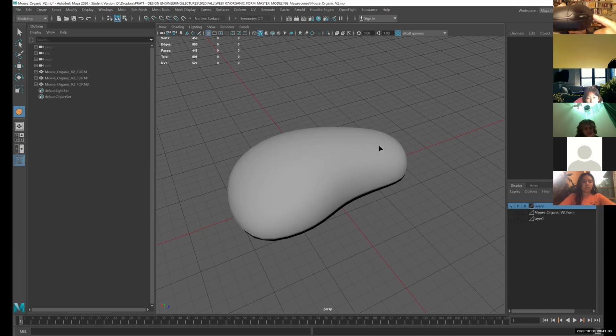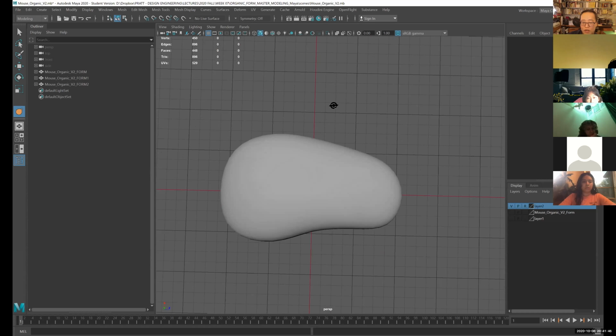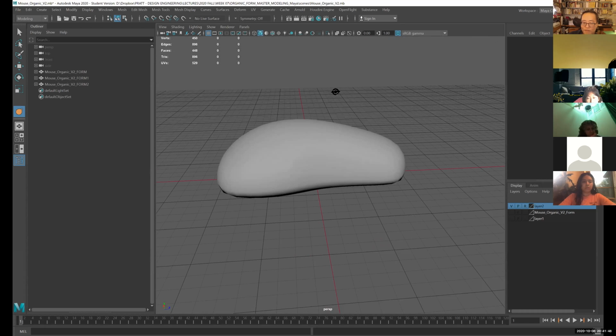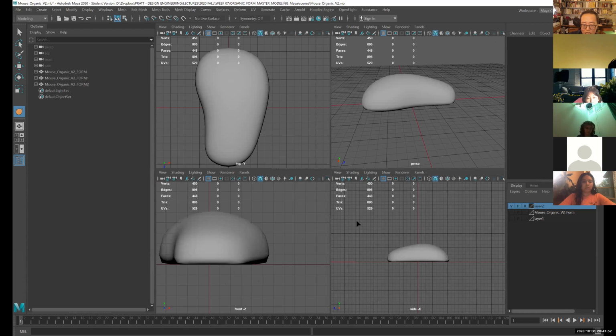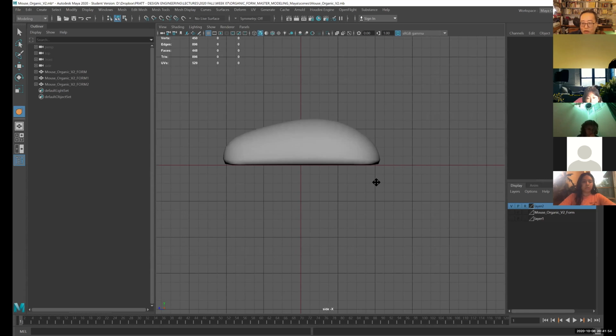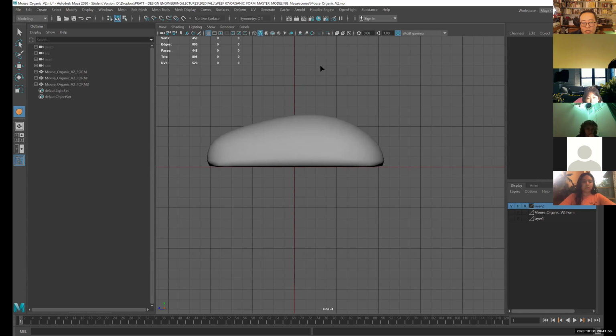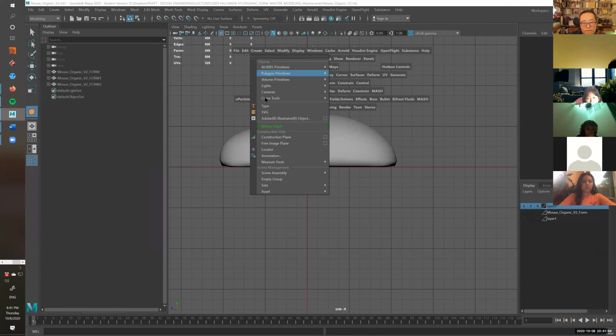So this is one button that is cut here and here, right? So what I'm going to do is produce surfaces that represent those cutting boundaries, okay? So there it is. Let's go to the side view and draw a curve. This curve drawing is under Create, Curve Tools, CV Curve Tool.